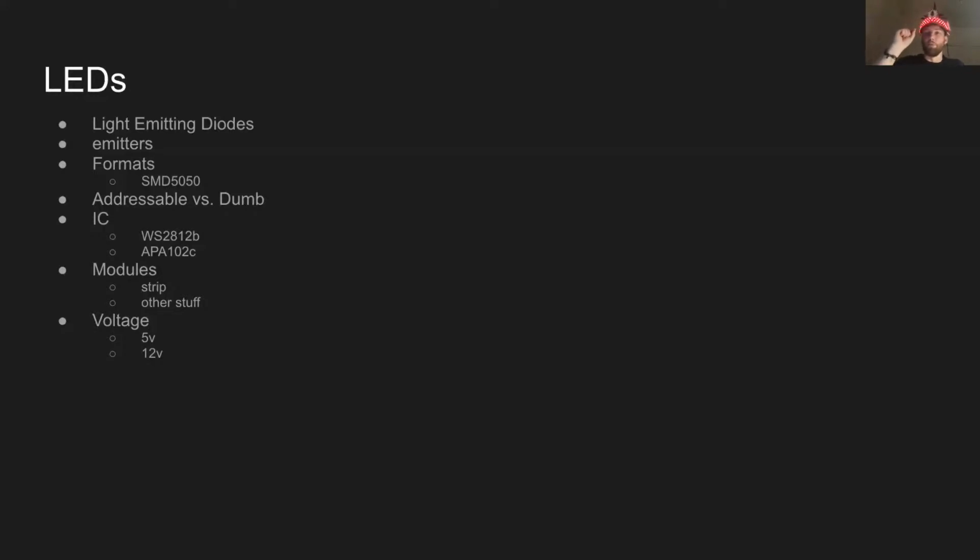And so there will be more distance separating each address, which ultimately leads to lower resolution if you're trying to get something really detailed. So my advice is typically it depends on how far away you think the audience is going to be from the object that's covered in LEDs. For a wearable, I like 5 volt single emitter pixels. And for stages and installations, 12 volt and upwards of 12 volt can be great, okay?